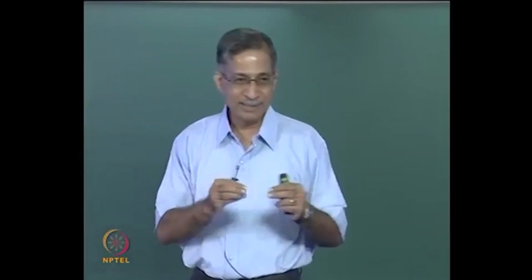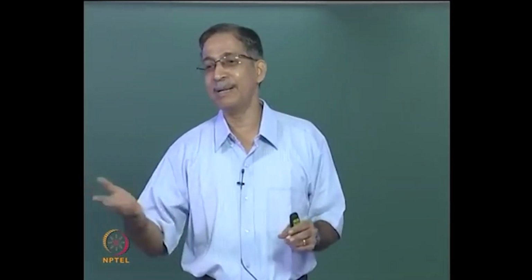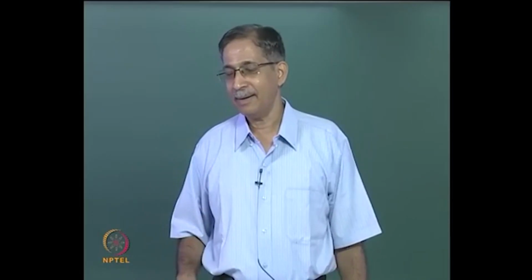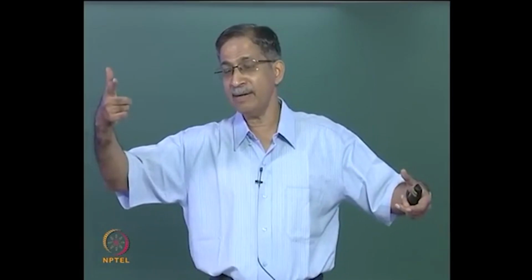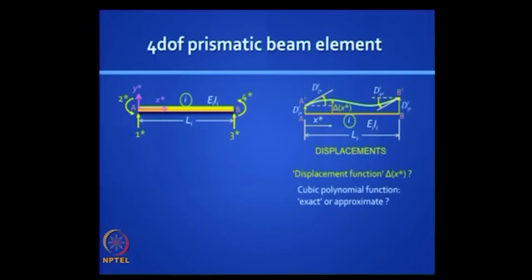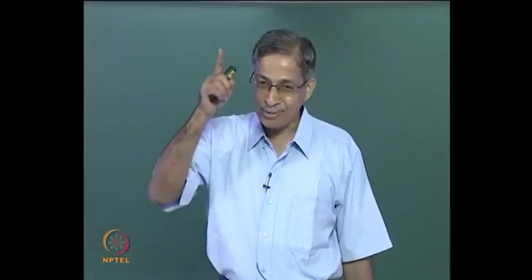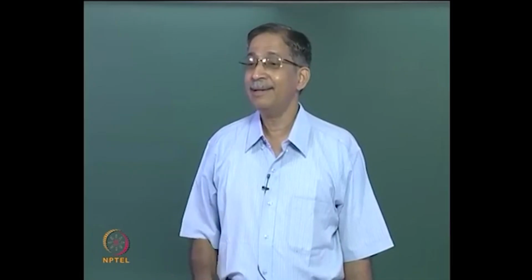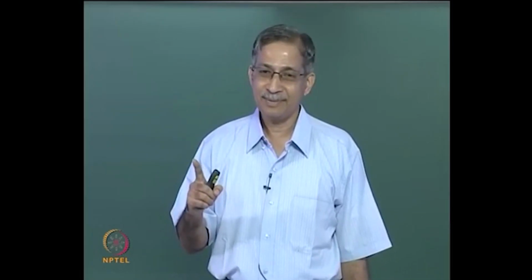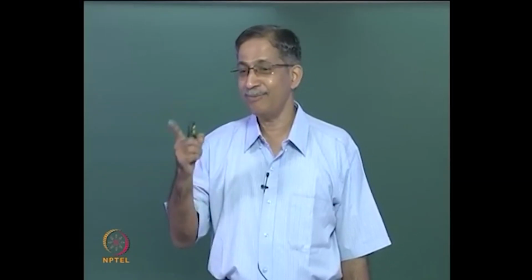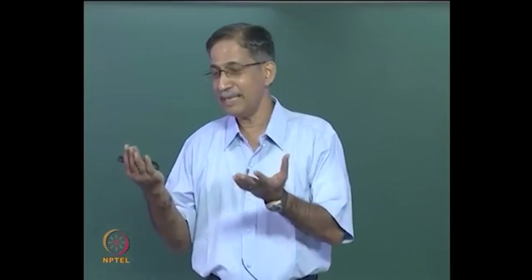So we are trying to get rid of intermediate loads in all displacement methods through equivalent joint loads. So your bending moment can have two different values. Here also you have F2 star and F4 star, they need not be the same. So you have a linear interpolation between the two end moments to get the bending moment at any section. Can you use that? Curvature is linear. So slope is quadratically varying, and so deflection. So you are dealing with an exact function.